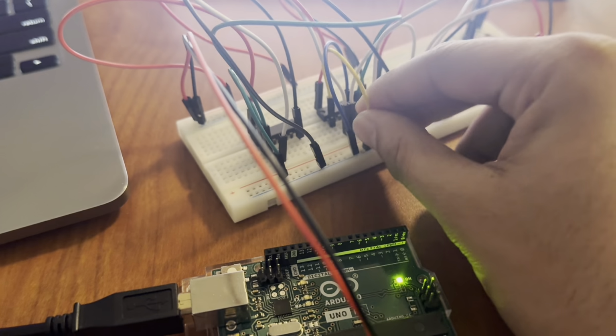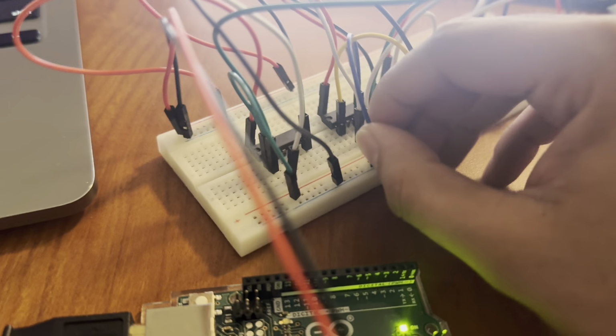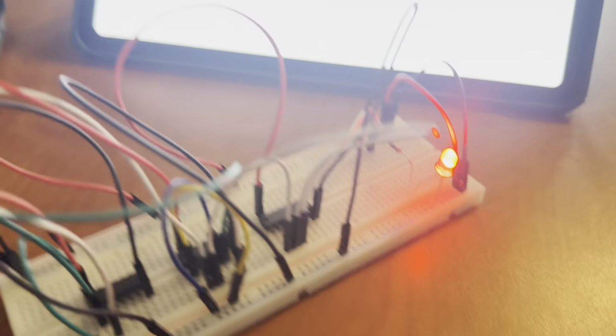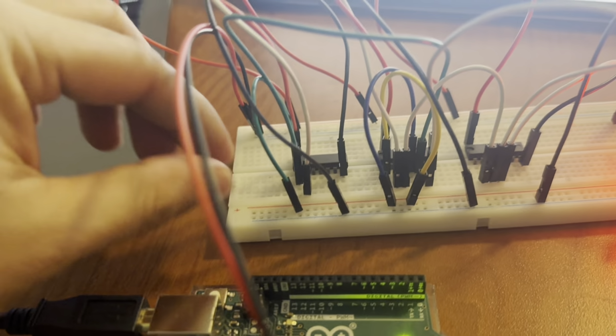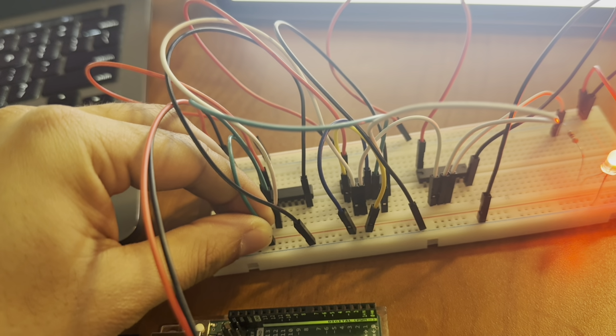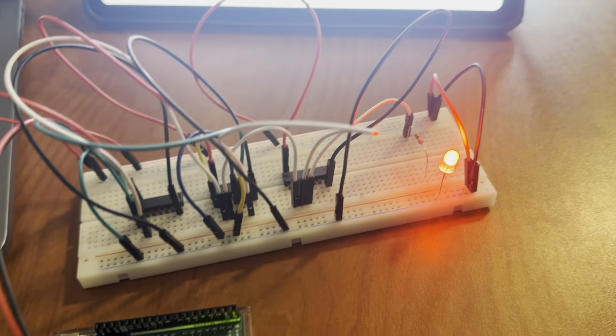If I want to put my input A to high, I'll put that to 5 volts. And if I want to put my input B to 5 volts, that will result in our LED lighting up. And so that's our truth table following what's supposed to happen. If we were to run the case where we have our selector being 0, or to ground, but our input A and B, remember A being yellow, B blue, is high, then it should remain high.